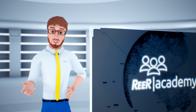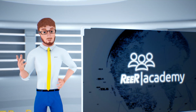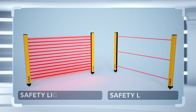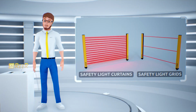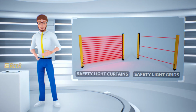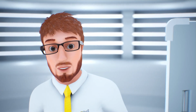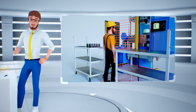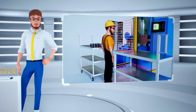As in the previous episode, I will be talking about specific safety devices, safety light curtains and safety light grids. Since the main function of the light curtain is to detect parts of the human body, fingers, hands, legs interacting with the machine, the predictable maximum operating speed of the machine should be considered.